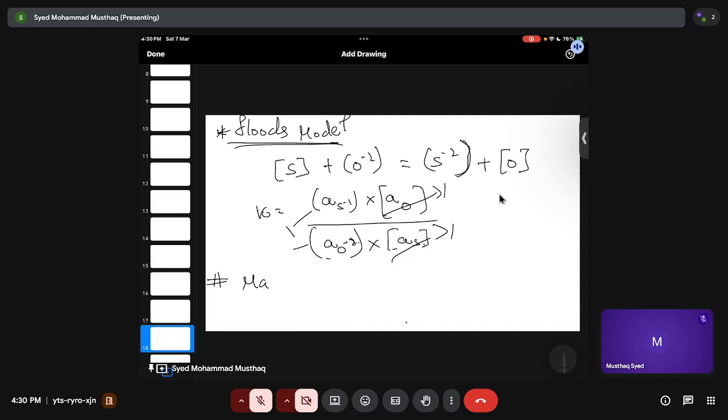There is another theory called Mason theory. Now here we have discussed that there is a complete dissociation of slag. That means there is no interlinking or bridging between your compounds. But Mason theory involves the bridging. So that means you still have some bridging, not complete dissociation. There is some dissociation, breakage of chains, but you still have some bridging.